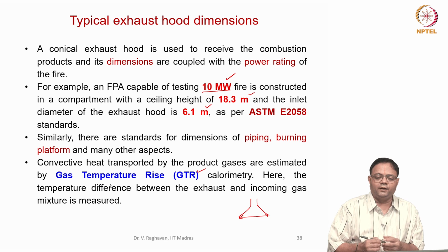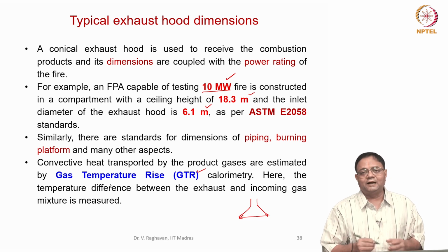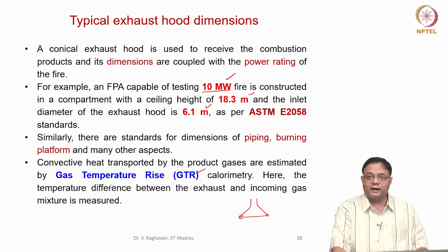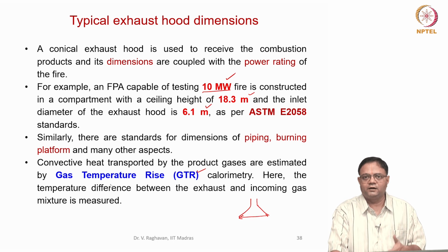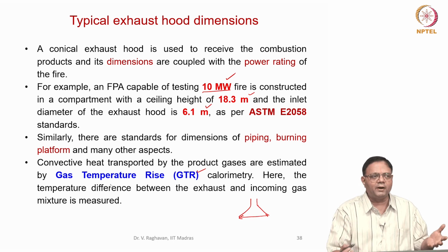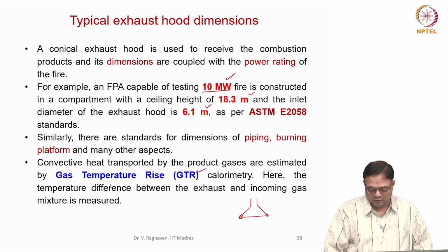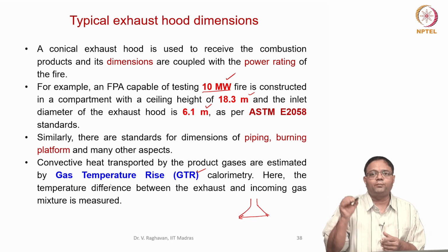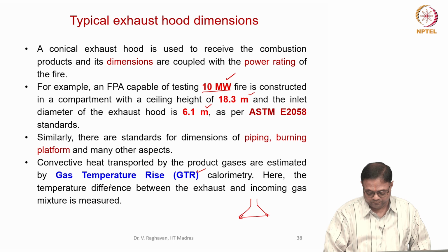Okay, so typically there are several standard techniques which can be used to determine the flammability characteristics of materials: ignition characteristics, flame spread characteristics, mass burning characteristics, etc. Then flame spread rate. Then we can also measure the ignition heat flux, the critical heat flux at which ignition can occur, ignition temperature, etc. And several combined parameters can be formulated. Then categorization of the materials occurs. Based upon the category, we use them for several applications.